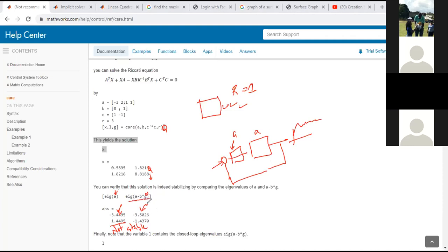And you see that now when you apply the gains that we're going to show you below, the values mean that it is stable. So the solution that we have is a stable system. So therefore, you know that stability means that it's going to go to a final value. All right. So that's why I said that you're interested in